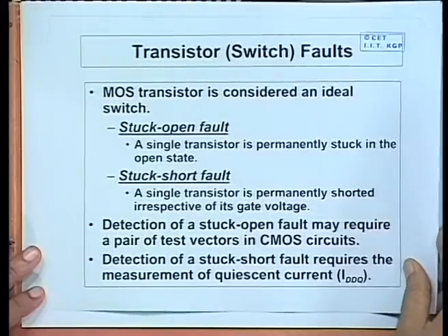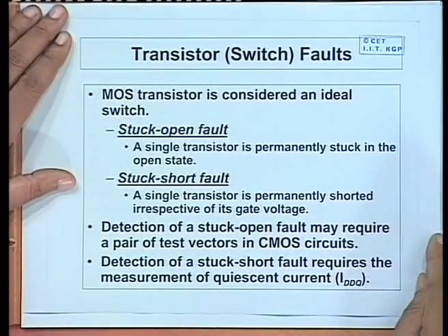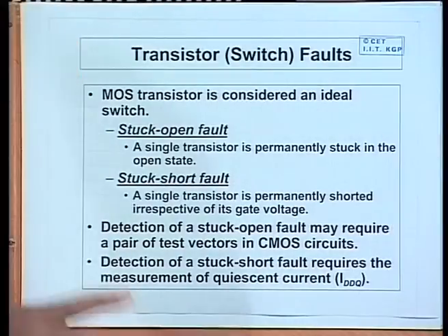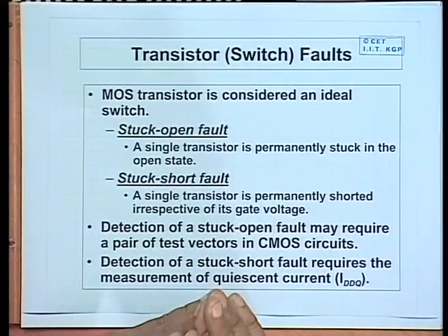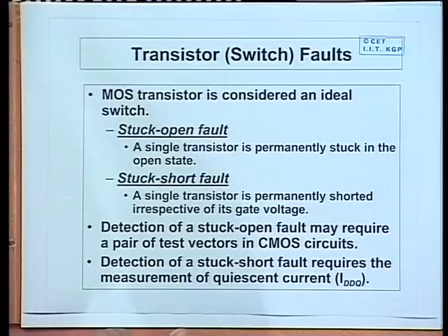So, these are the most popular gate level fault models which people use. Now, we also sometimes consider transistor level fault models because of two things. Number one, most of today's VLSI circuits are designed using MOS technology, they are CMOS.